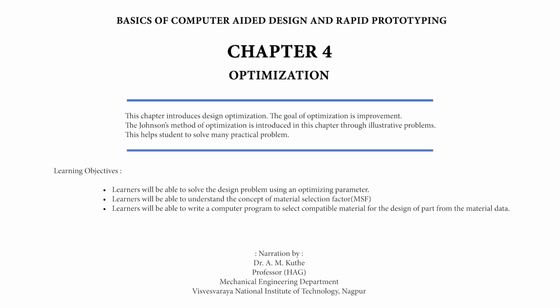To identify the variables, it is necessary to know which parameters are not variable. The parameter to be optimized is not a variable. The material constants like Young's modulus of elasticity E, shear modulus G, Poisson ratio mu, and yield stress Sy, etc. are also not variable. In this problem, parameters delta, Sy, and E are not variables, while the parameters F, L, Fs, I, Z, M, d, Sb are variables.